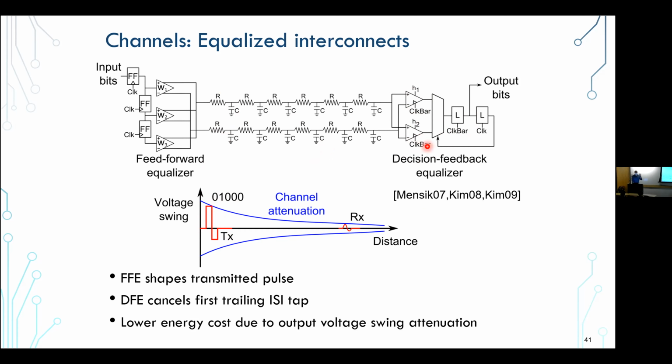I don't want to go too much into these equalization techniques, that's for another class, but people were trying to do some, let's call it mixed signal things that are not necessarily digital. And I'll show you there's some benefits to that. You can basically signal across without adding inverter delays. So you're very close to, quote unquote, speed of light on that segment, so you can shrink the latency.